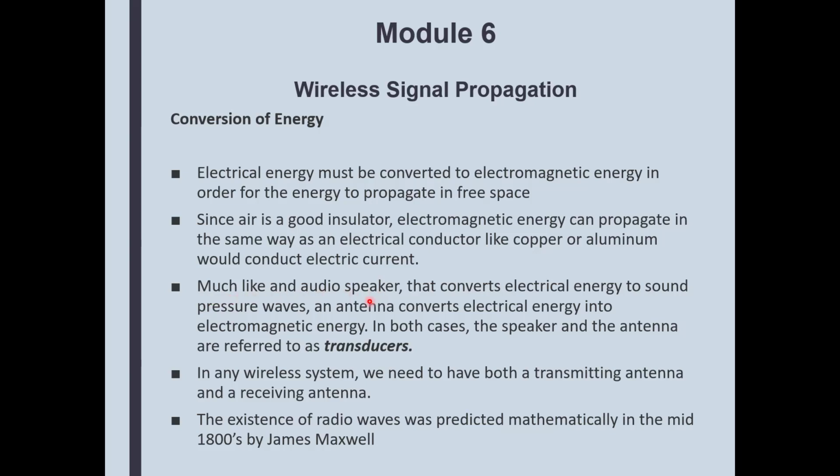Much like an audio speaker that converts electrical energy to longitudinal sound pressure waves, an antenna converts electrical energy into electromagnetic energy. In both cases, the speaker, or the loudspeaker properly called, and the antenna are referred to as transducers. And as we remember from the telecommunications model, for the most part, the input and the output would be a transducer.